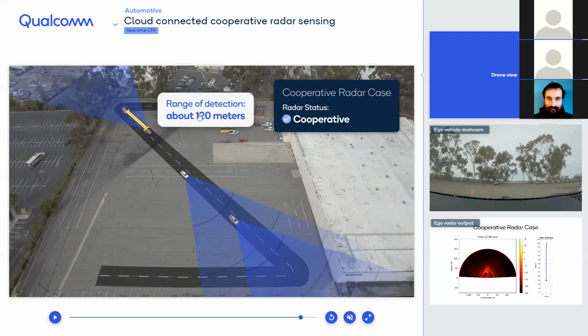If you are doing TDM, then you are reducing the frequency that radar samples can be generated, and also reducing the maximum range that you can detect. If you are doing FDM, then you're reducing the bandwidth, and that reduces the resolution of the measurement. So all those things, even though they are feasible in principle, come with a cost.